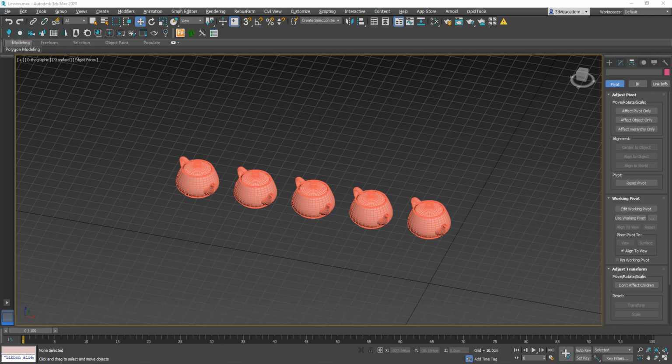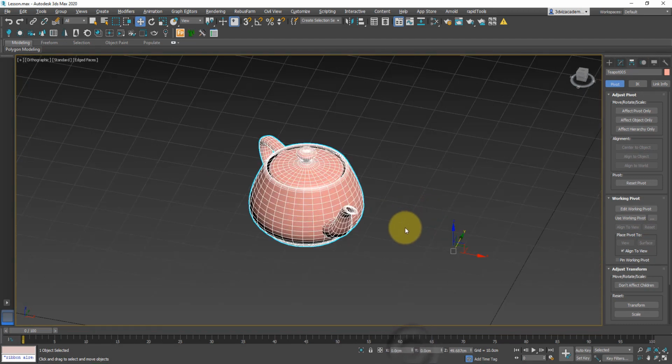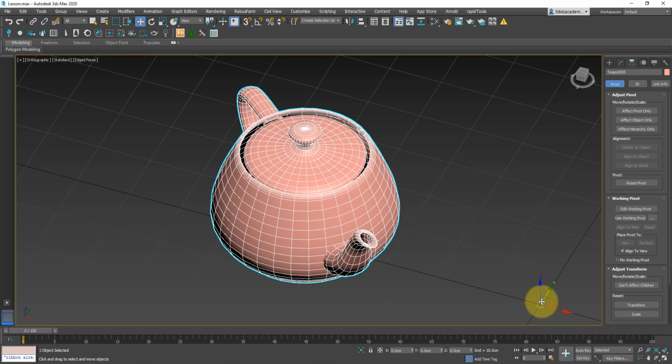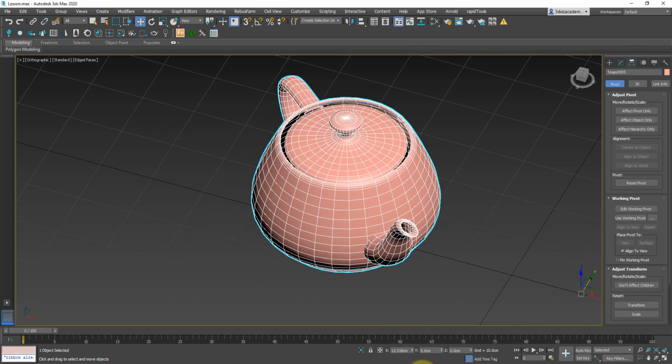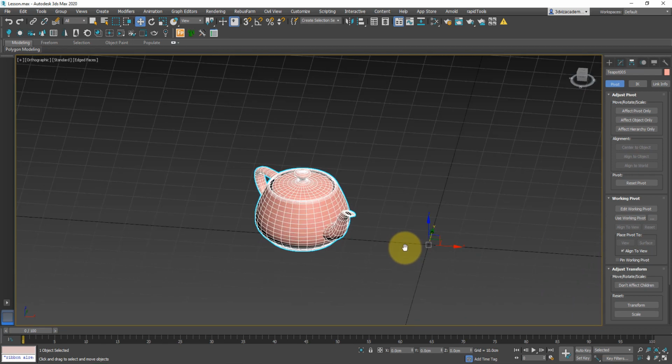Now we already know quite a lot about 3ds Max, so why not try to explore this modify panel a little bit more. Let's just put our object closer to 0 point. As you can see now it's pretty much almost at 0, but only with its pivot. And how did I type in those zeros? You can select those brackets here and right click on any value that you already have. By right clicking on it, you're going to instantly move it to its lowest nominal. So in this case, it's 0. So our object pivot is actually on 0, 0, 0 right now.